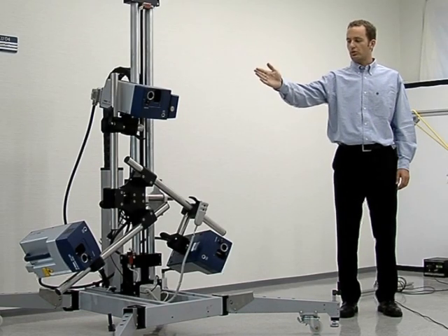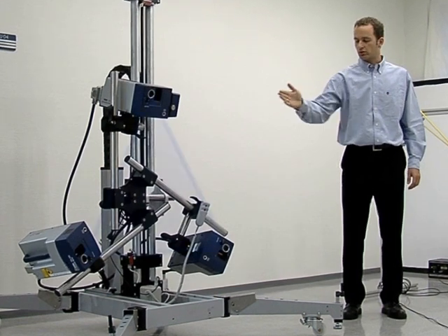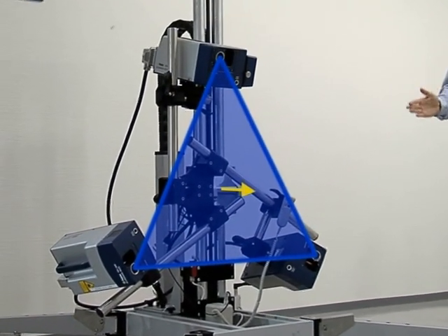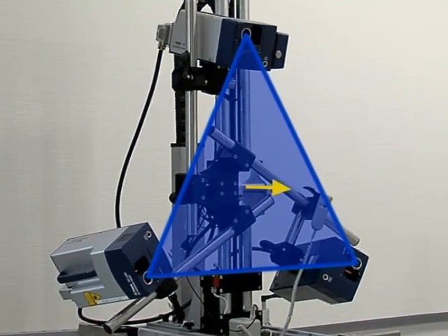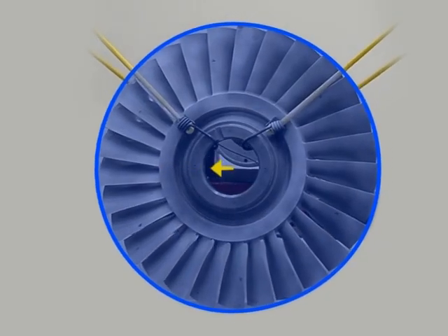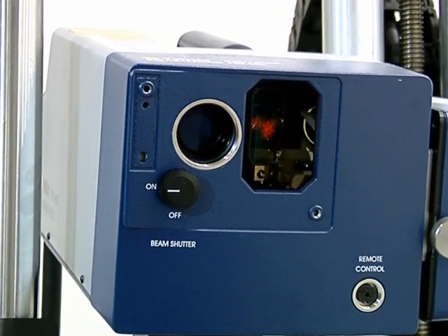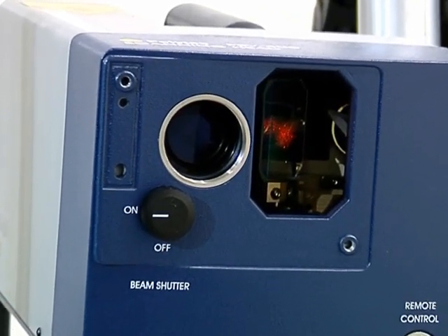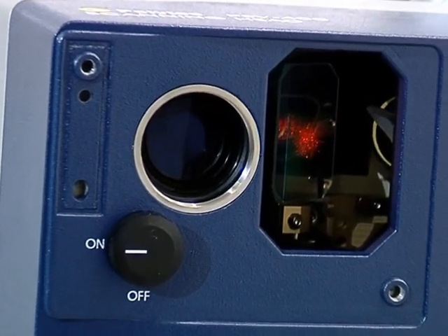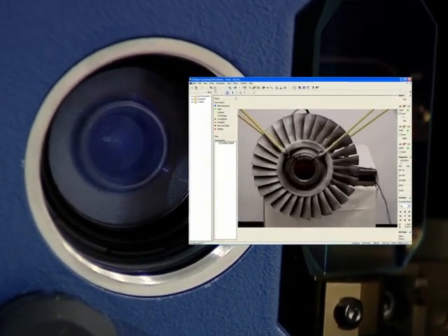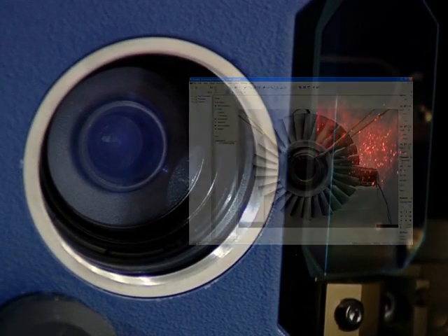Typically, the measurement heads are positioned at the corners of an equilateral triangle. In a proper setup, the triangle's surface normal coincides with the average surface normal of the measurement area. After mounting and cabling the heads, the power is turned on. An internal video camera provides images of the object under test as seen from the measurement heads. These images simplify construction of measurement geometries and provide for an intuitive animated visualization of the measurement results.